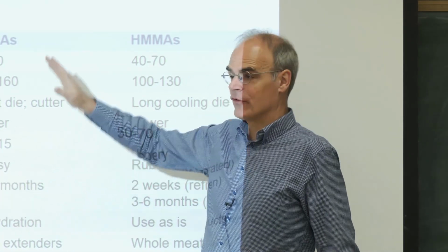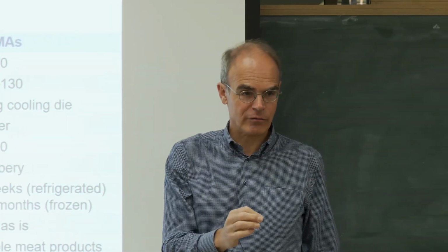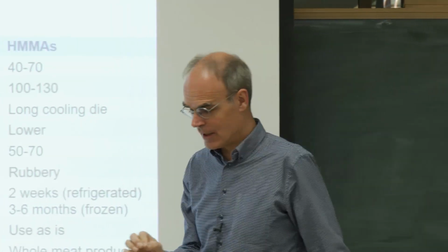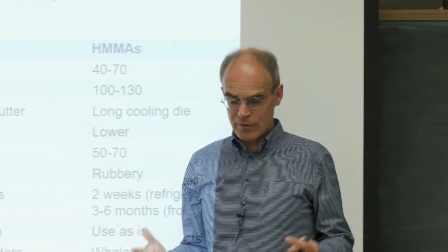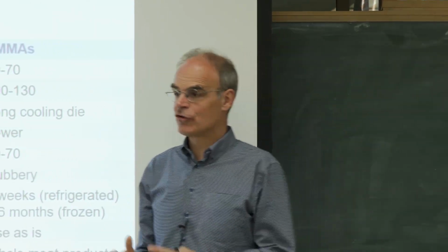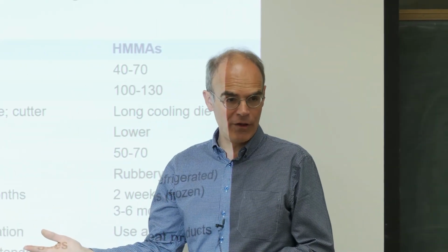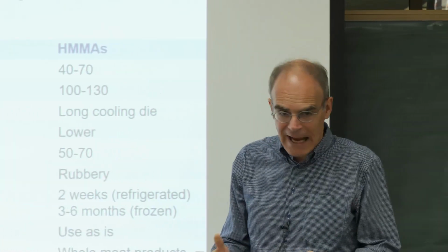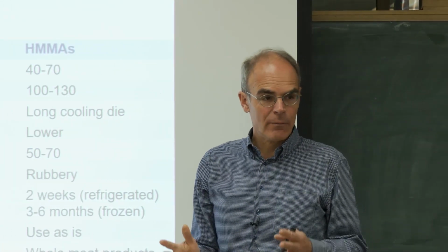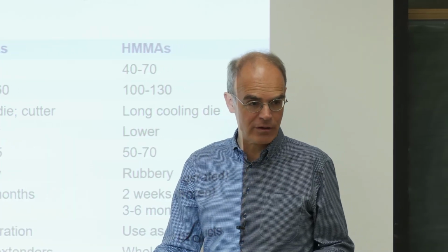And there's another factor why TVPs are still used, which is just the scale of production. I mentioned to you yesterday that visit I made to a pet food factory, and of course it's a cereal-based product, but with just the single screw extruders we can produce tons and tons per hour. We can just keep the whole thing running. With high moisture extrusion, even though we scale it now to some extent, production scale is still way smaller than that of low moisture extrudates.